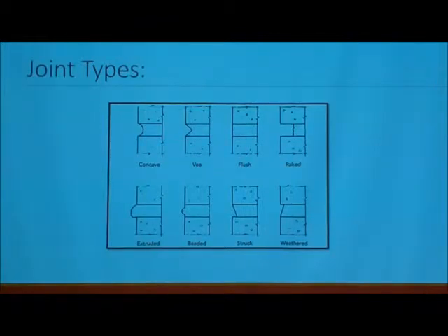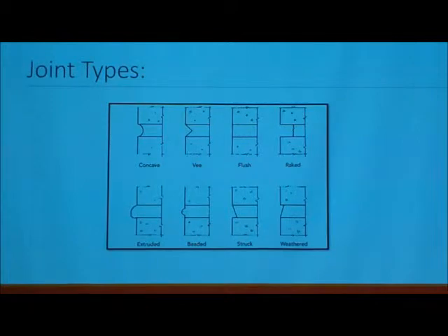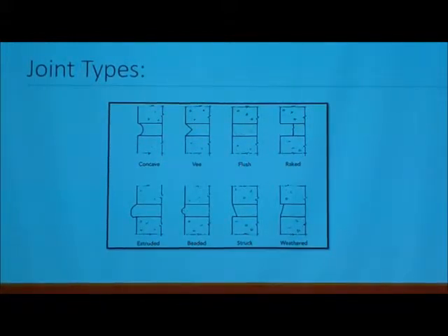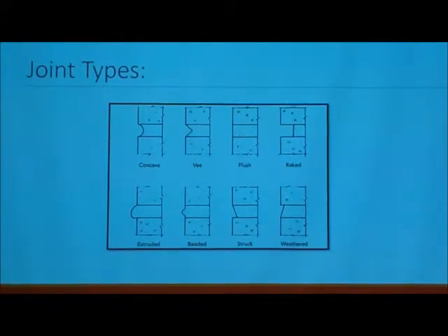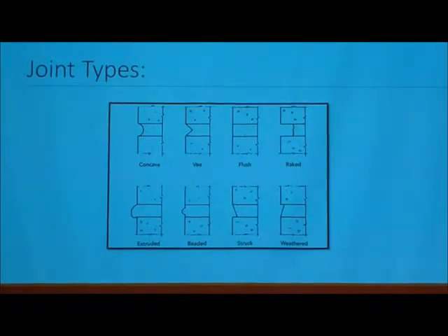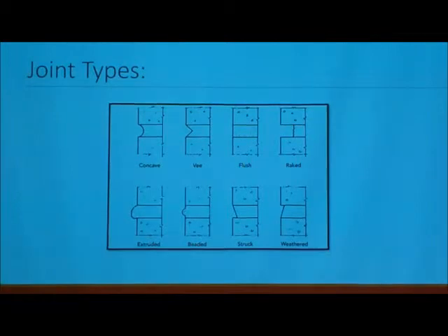Now we're going to talk about some different joint types. These are different joints that do different things, and you can specify joints based off of what performance you want. Concave joints and V joints are typically done because whenever you lay the mortar in there and then stack the bricks, you come back out with the trowel and push this in, so that creates a very dense surface right here on the edge. That prevents water absorption into your wall.